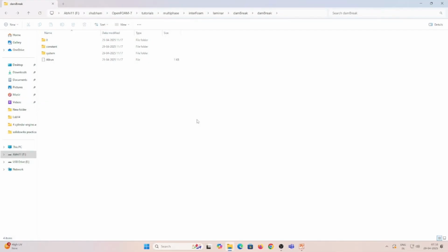Whenever we work with fluid dynamic simulations, we need to calculate the fluxes of momentum and of the reference phase, which will be crossing across the volumes. If our cells are extremely distorted, we will not be able to make a correct approximation of the fluxes. That's why the quality of the mesh should be within reasonable limits. In the blocks, the word HEX was written, and after the hex, we did all the uniform gradings parallel to the sides.